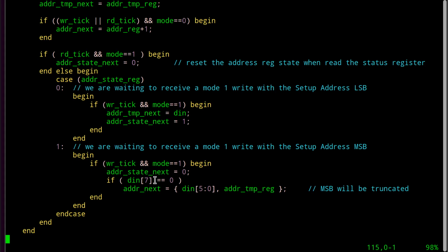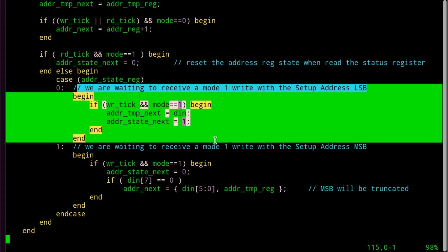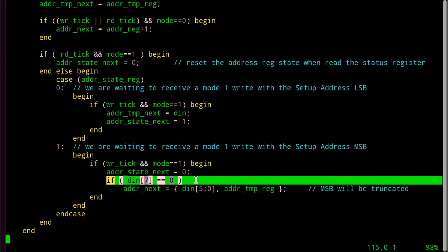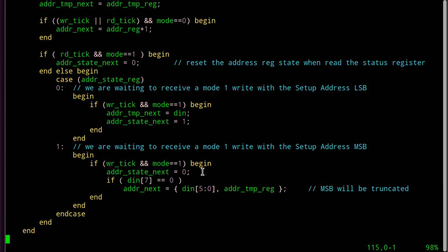All right, now this is going to happen. We're going to come in here, and we're going to store stuff in this register, and that's going to happen every time the CPU wants to write into one of the VDP config registers, because it will do this in this state 0. But when it comes down here and it's doing its second access to a VDP register, it won't come down here because that'll be a 1. And as I look at this and think out loud, I'm not sure this is right. Because if that's true, we do want to go, oh yeah, it does, okay.